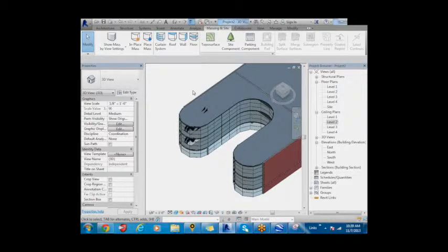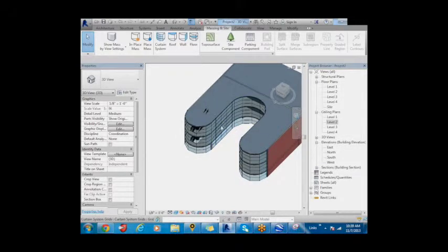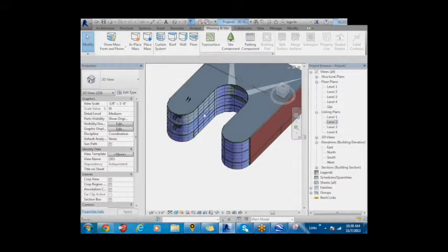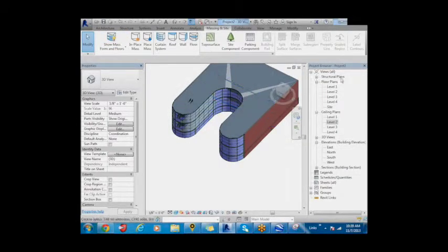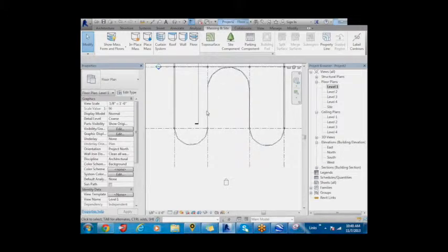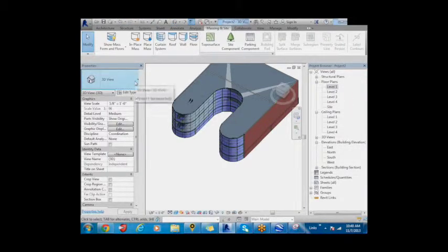I think there was one more thing we wanted to emphasize before I hand it over to Glenn. Within conceptual mass, say you wanted to put in interior walls. It allows you to connect your interior walls to regular type walls. By regular type walls, I mean vertical walls that aren't slanting. When you have slanting walls, it wouldn't allow you to connect to it. The best way to explain is to show it. Glenn, do you want to do that as part of what you intend to cover, because we have only 10 minutes? Just let me know. Sure.